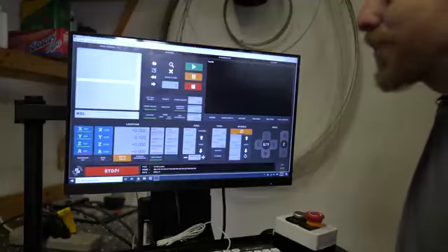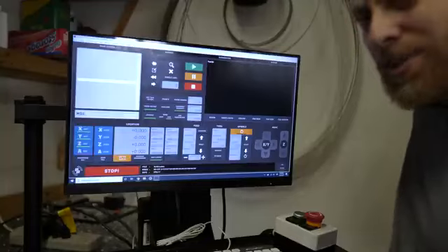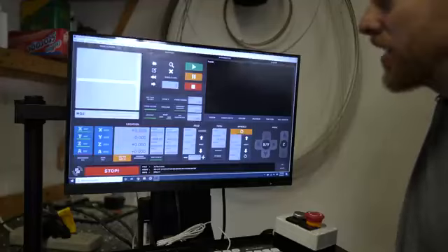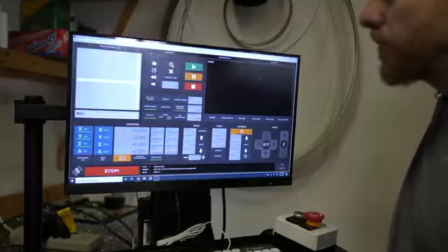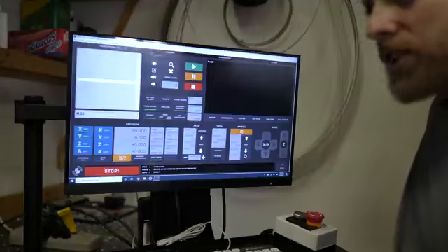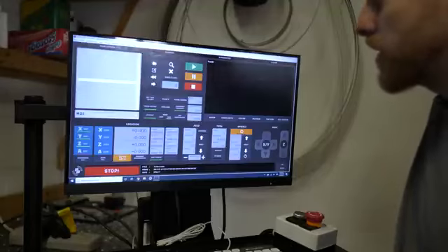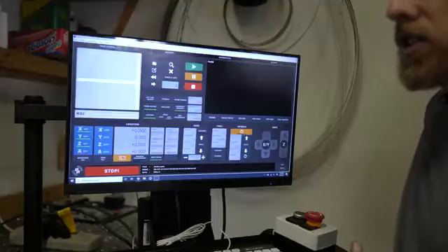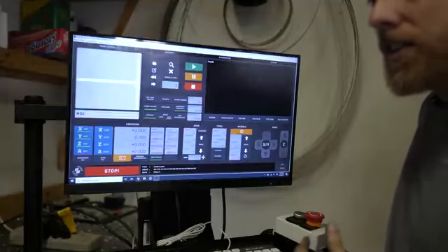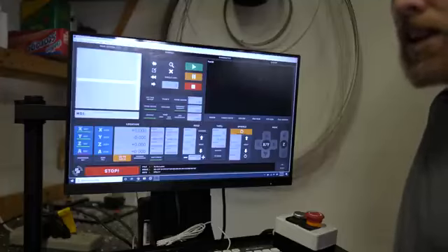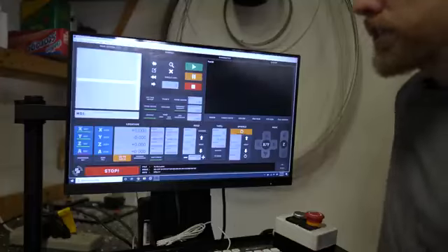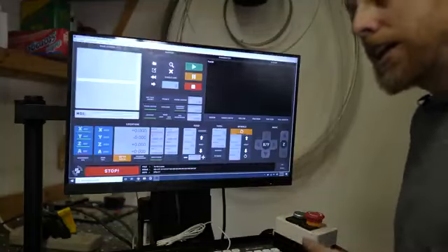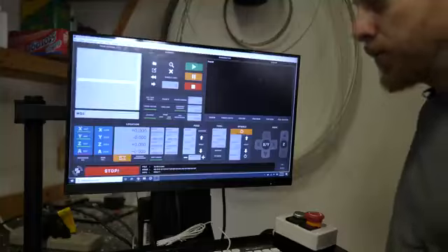I think actually most people that use Mach 3 probably aren't CNC experts either, and I found there's a lot of kind of weird habits going on. Like setting up tool heights is not really very common for Mach 3 users. They don't use the actual tool offsets. They just set the Z0 at the bottom of the tool every time they change tools. This makes sense if you're running a router and you just have to physically pull a tool out and put it back in, and you have no idea where it ends up.